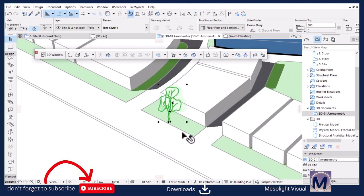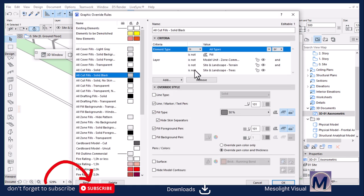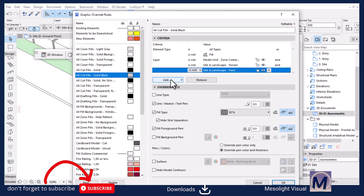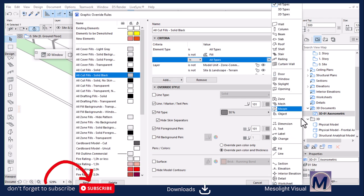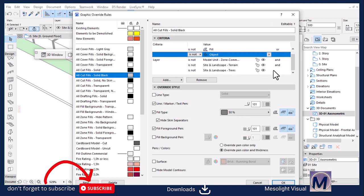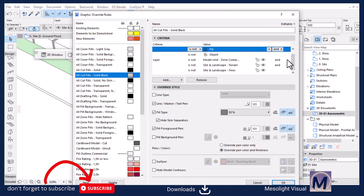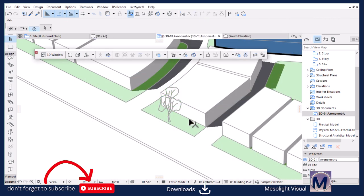What's the problem? It didn't change. What might be the problem? Because in ArchiCAD we were using the layer. We could have used the element type as well, and then make sure it's what? It's an object. We say it's not, something like that. Then end. Hit OK. Should be fine now.